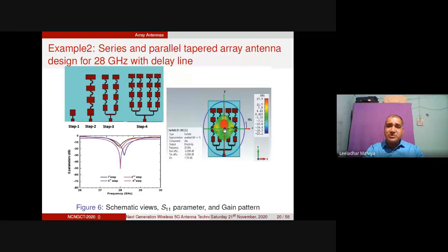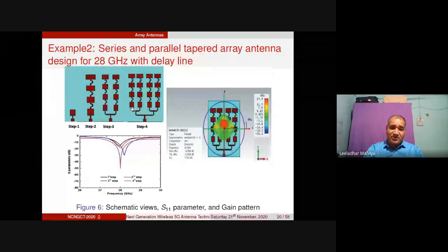Right. So can we do certain corrections in this design? Yes, definitely we can, because in step 3 we have a 1x2 feed arm, right? And that feed arm is made up of a quarter wave section, 100 ohm lines, as well as a 50 ohm impedance. If you look at another scenario here, step 4, you have 1x2, then again the 2 arms are divided into 2 arms, so this has become 1x4 into 4, right?